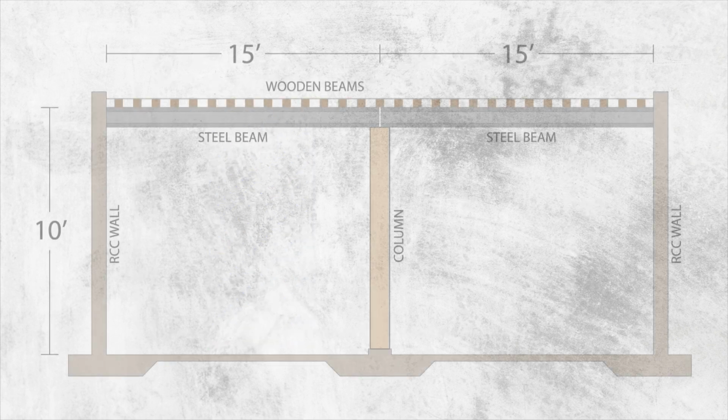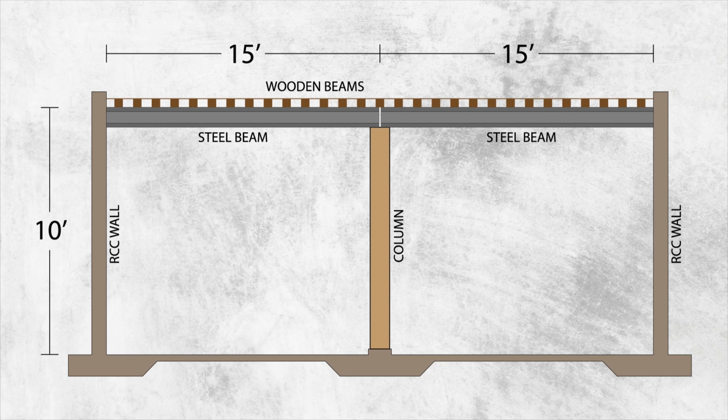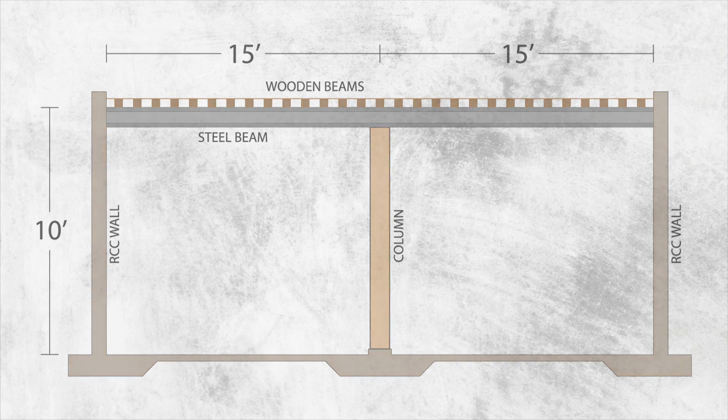This is the section view of our basement. Basically, we have two options. Either provide 6 15-foot-long simply supported beams which are not continuous over interior columns, or provide 3 30-foot-long beams which are continuous over interior columns.